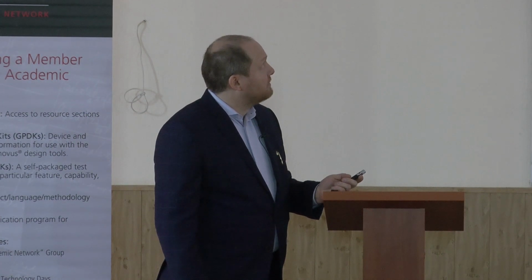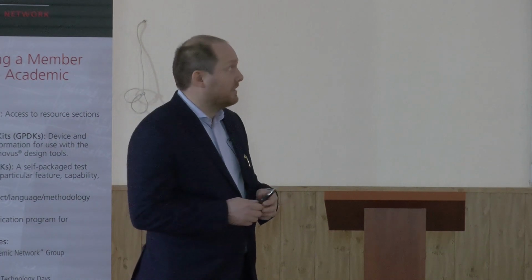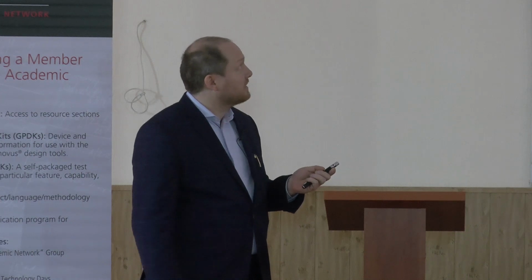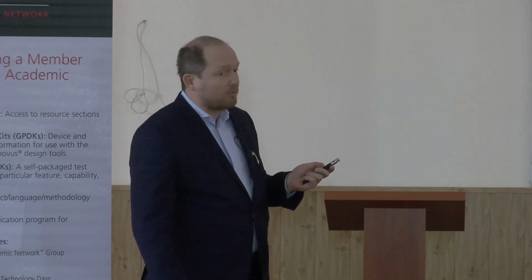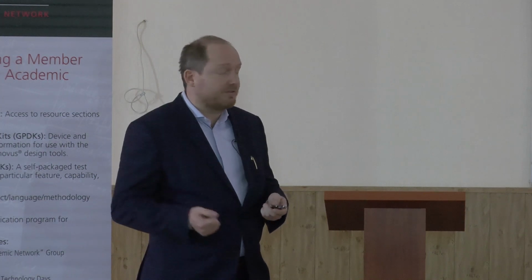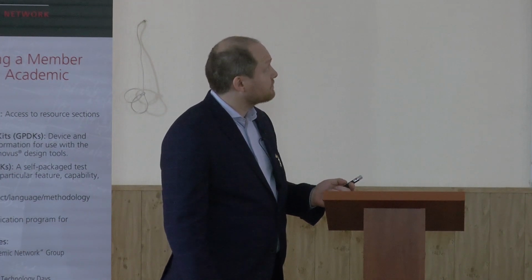Then, PPA stands for power, performance, and area. These are the three elements which can be optimized in a microelectronic system. Power is the power consumption. Performance is how fast the circuit is, and then the area. The smaller a circuit is, the cheaper it is to produce.